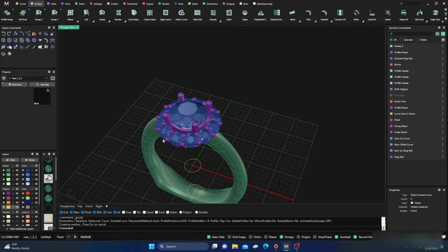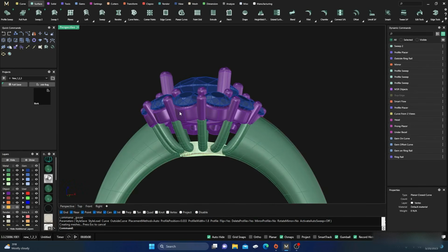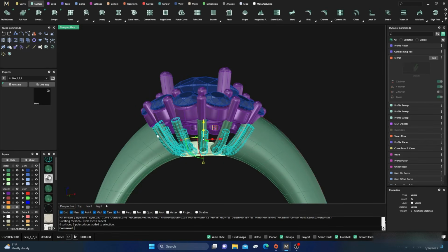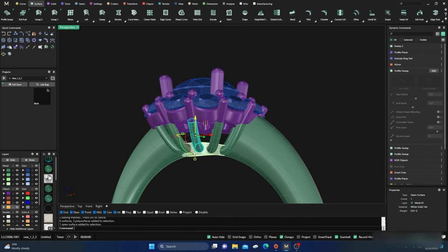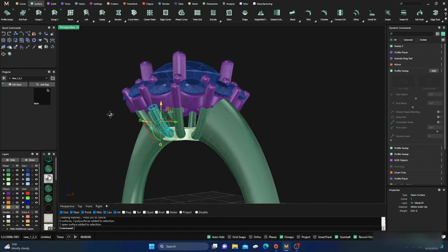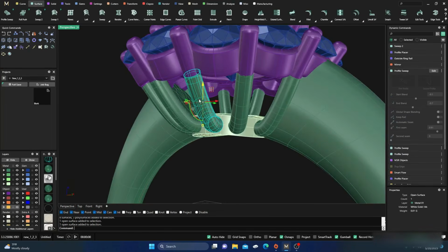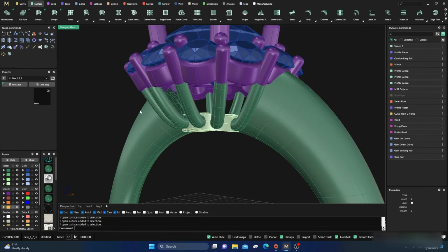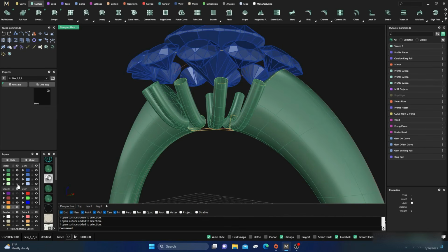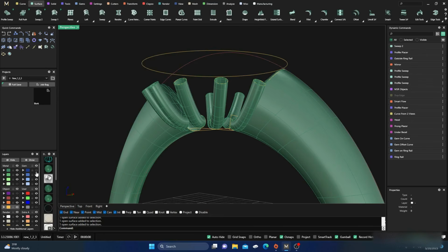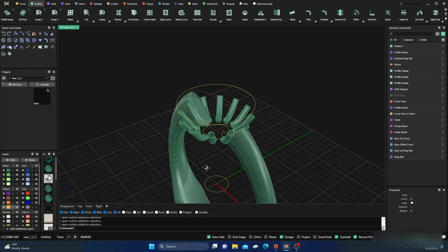These are all open, right? So really you only have to do one side, and it'll mirror, right? What you'll need to do on this is kind of tricky. You don't want to cap them. If you cap them, you break history, and they won't update. So what you have to do is kind of go in there and do it manually. But it's really not a big deal. I'll just show you one of them, and then when you're ready to do yours, we'll just let you know how to do it.